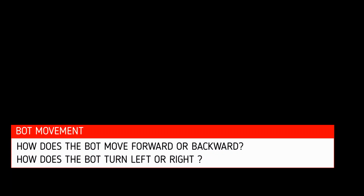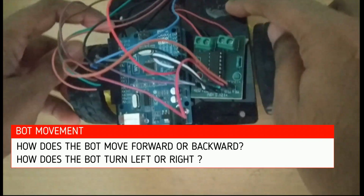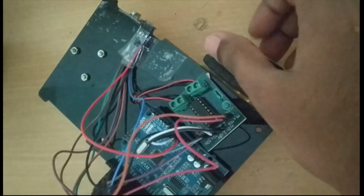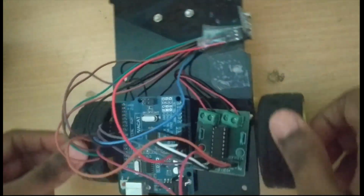Before going into the coding part, we need to understand how the bot moves. For forward and backward motion, both the wheels have to move at the same speed in the same direction. But for a left turn, the left side wheel should move backward and the right side wheel should move forward. And for turning right, it should be the reverse of the left turn motion.